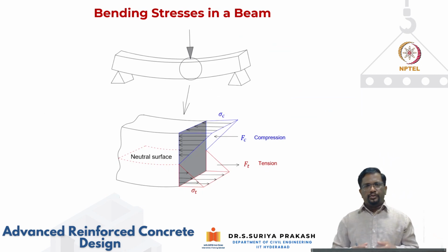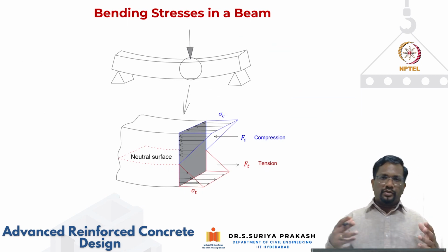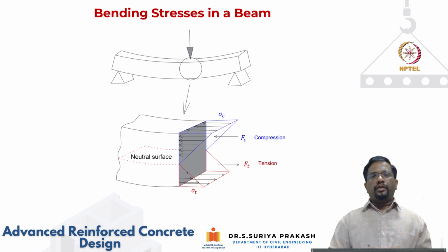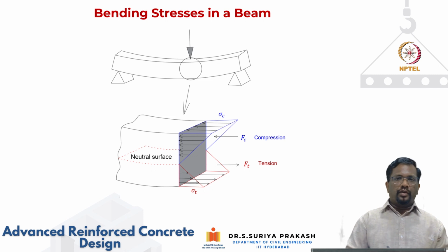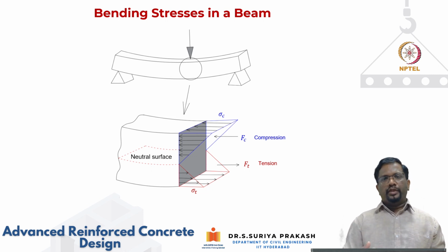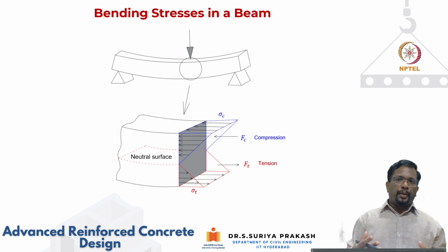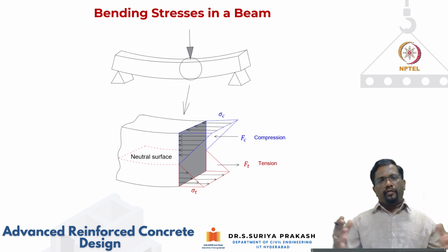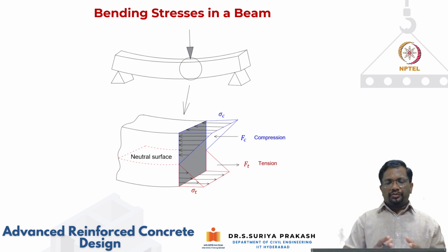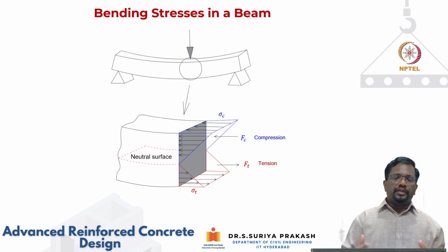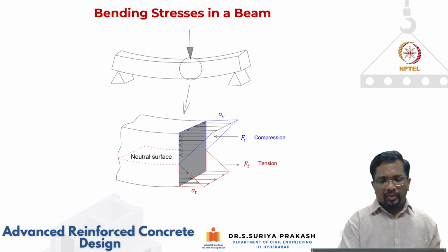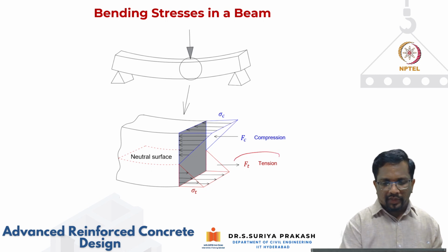And with respect to concrete, we know that concrete is very good in resisting compressive forces. However, in construction, usually the flexural members govern the design, and we always want to have large column free space. So when you try to span a structural element, the limitation in capacity is actually controlled by the tension capacity, right?